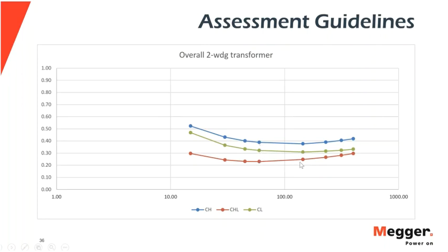through this frequency here. But if my cursor shifted and these now became the 60 hertz points, sorry about that, or these became the 60 hertz points, then you can see that perhaps the slope isn't negative after all anymore, it's actually positive. And so that's why the temperature piece becomes so critical in the analysis of narrowband DFR test results.